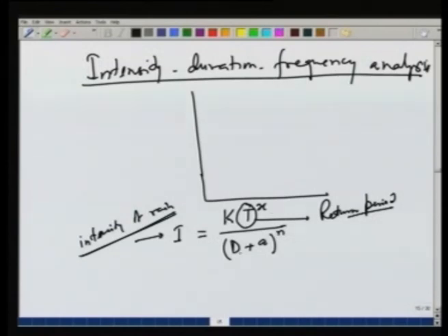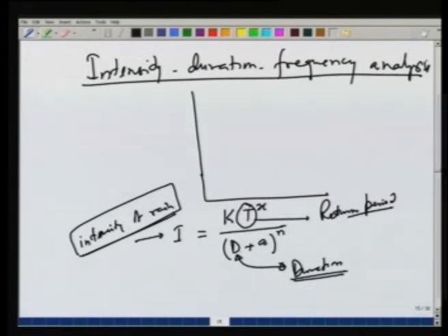The duration is also affecting the intensity. So, we can say that as the duration increases, the intensity will decrease. As the return period increases, the intensity will increase.